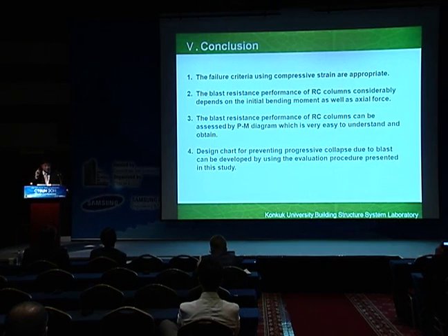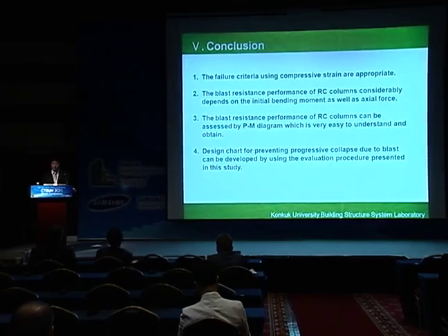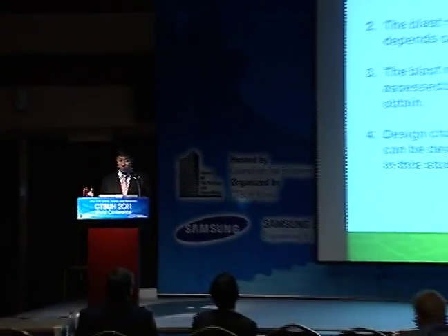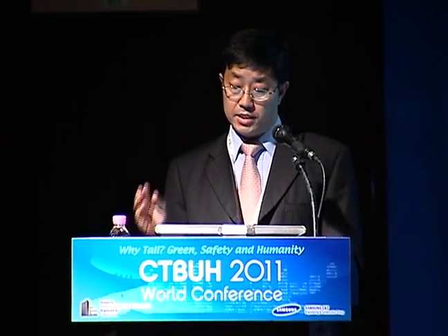Okay, let me wrap up my presentation by giving this kind of conclusion. We use the compression strain as an index of failure, and the compression strain is very appropriate for this kind of research. Also, the initial stress condition, which came from bending moment as well as axial force, significantly affects the structural behavior of the column after blast.